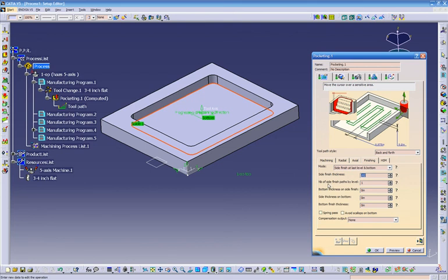Then it's going to ask us the number of side finish passes by level. So it's going to ask us how many passes we want. It says 1, bottom thickness, and side finish pass. Side, thickness at bottom, everything is common sense. And if you don't know what it does, you just click on the question mark. See, bottom finish. Let's make this 20,000. So right now I just give it a finish on the bottom and a finish on the wall.